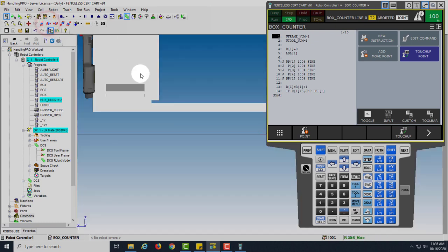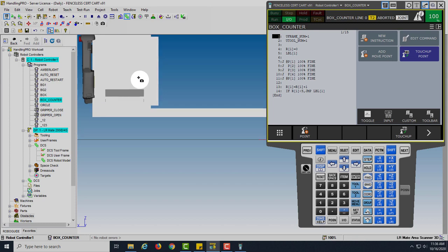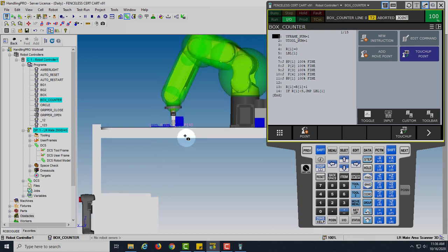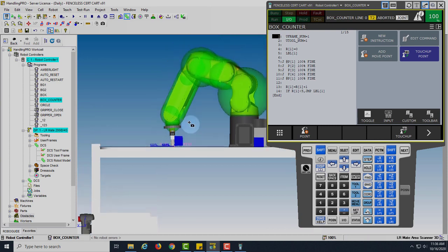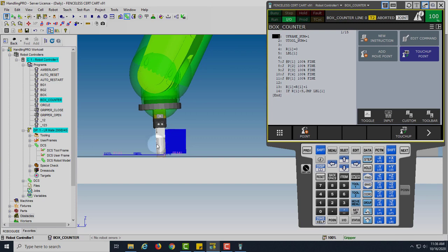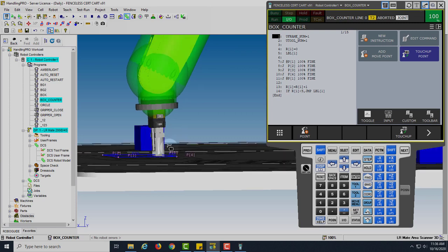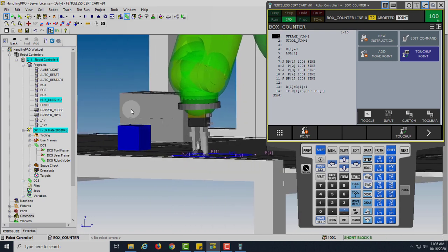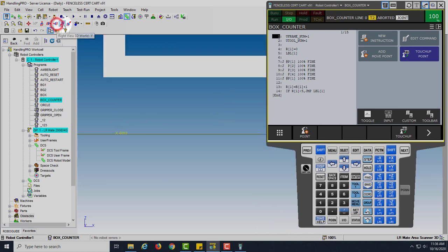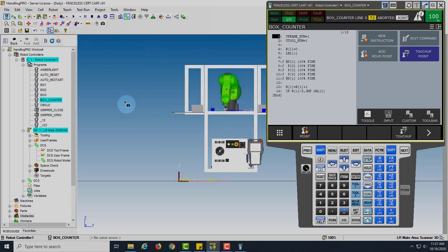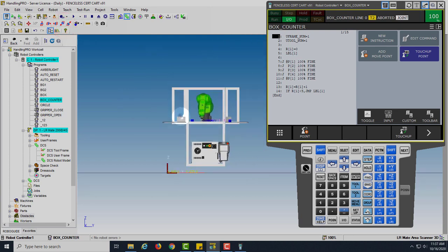We can look at a side view. And again, if it puts you in a different or weird position, remember, use that pushing down on the wheel or control right click to pan up. But here, this helps you give perspective of if I'm trying to move this part to be in line with my robot. This gives me another good perspective that I can see exactly where all of the parts and fixtures are located. So again, here's a couple of different other views that you can see right at the cross. Here's the front. So just be aware of those.